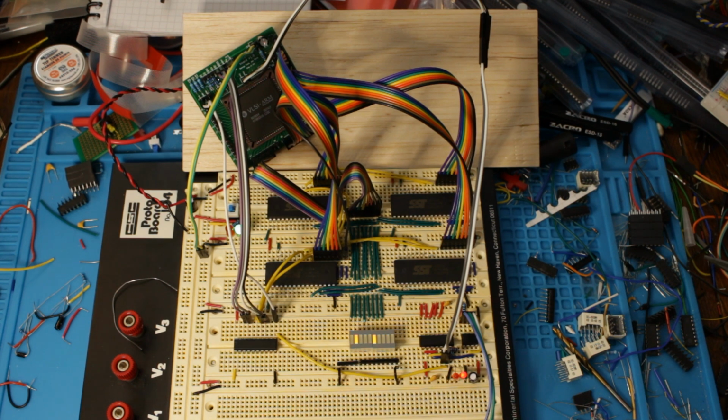Now, in fact, what the program actually does is jumps backwards 4 bytes on every instruction. So I put the same instruction in all locations in the ROMs. So what we should be seeing is the counter going backwards. However, because of the way the pipelining works, it takes, I think, 3 cycles for it to fully execute the branch instruction.